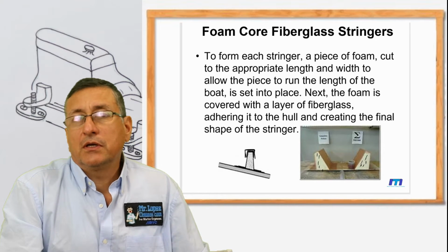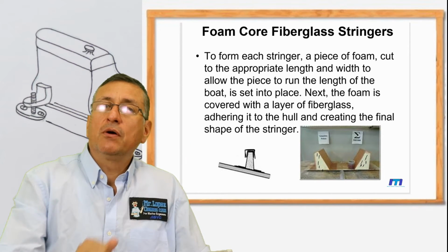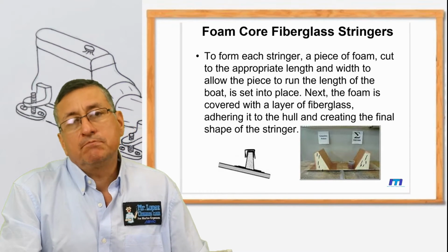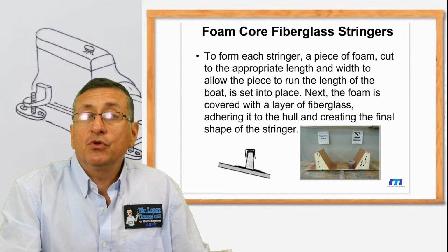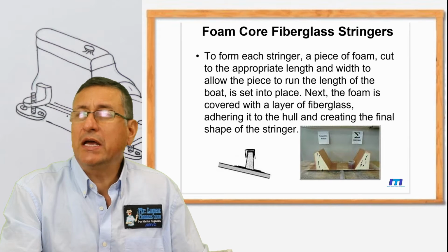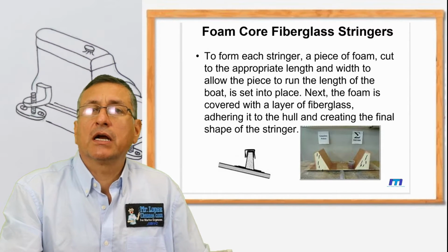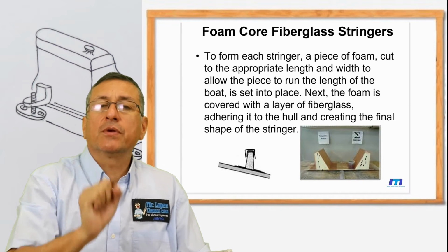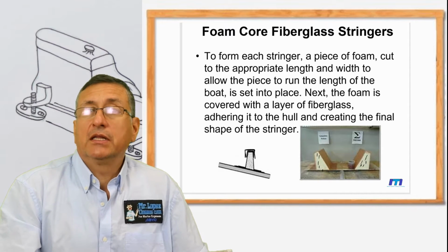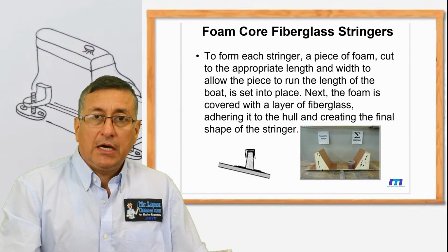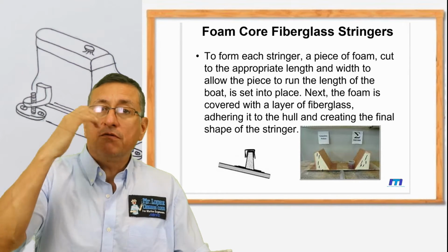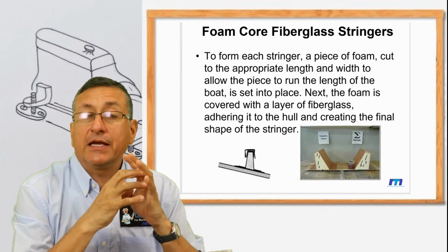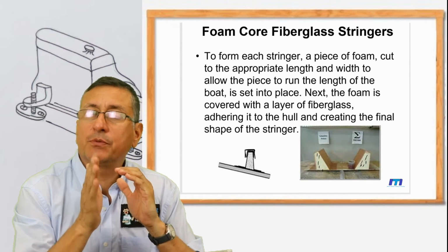In that conversion, one of the steps in the procedure to convert the boat from gasoline to diesel is to reinforce the stringers. Yes, because the diesel engine produces too much torque, twice or three times the torque that a regular gas engine produces. For that reason, the quality and thickness of the stringers should be better than the original stringers for a gasoline boat. And additionally, those stringers should be reinforced with aluminum in order to install the motor mounts properly. I am going to explain the process step by step.